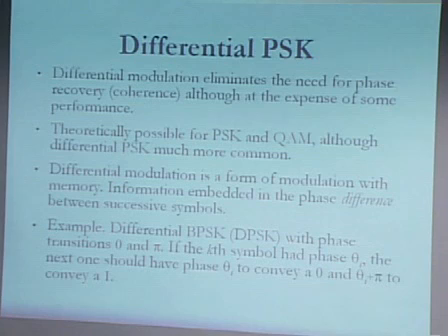There's a form of modulation called differential modulation that eliminates the need for phase recovery, although at the expense of some performance degradation. So in theory, one can use these differential techniques with both PSK and QAM, but it's very rare in QAM, so we're only going to talk about it in the context of PSK. Okay? So essentially, differential modulation is a form of modulation with memory. So rather than embedding the information in the phase of the signal, we're going to embed the information in the phase difference between successive symbols. Okay? So let's use a very simple example.